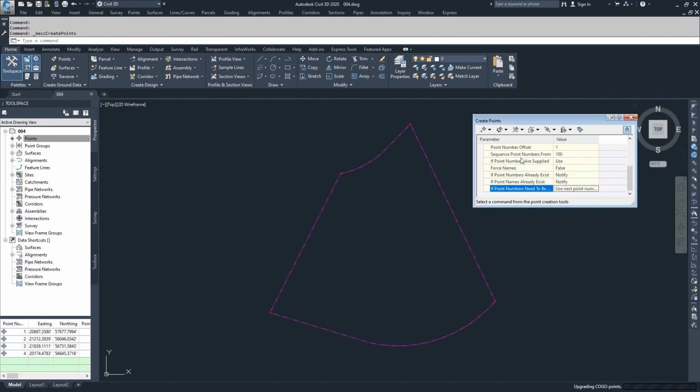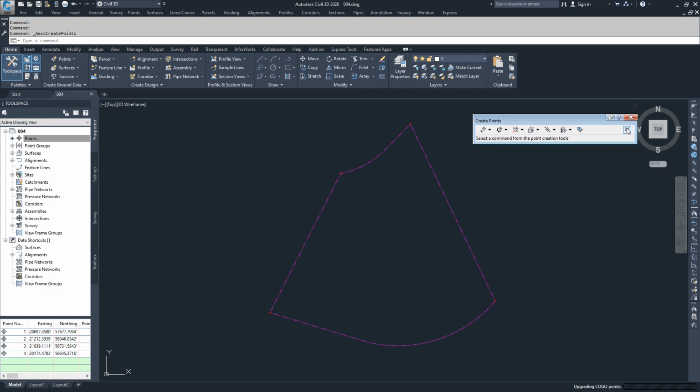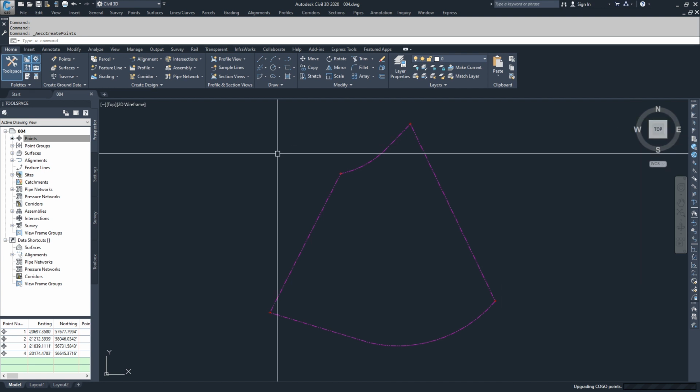When we created our points, we didn't set any of these parameters, so I know that I want to change these point parameters. I would have preferred to start my point identities higher because these are calc points. I don't want to have them on the low numbers that would come in from a survey. I want to set them on a higher number, something that I'm not going to have overwritten when I do a survey import. So I'm going to jump into these points and edit them.